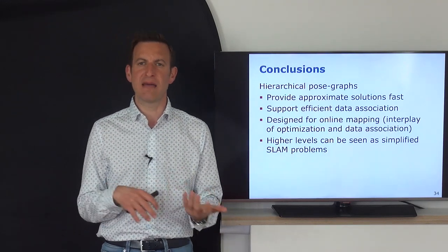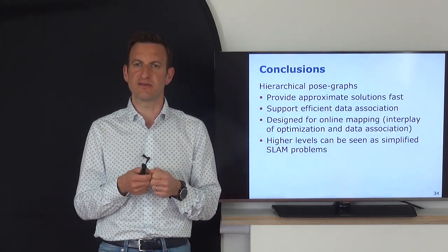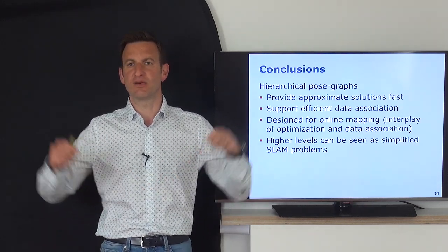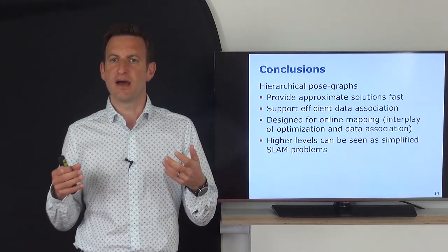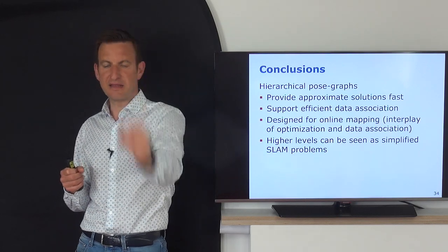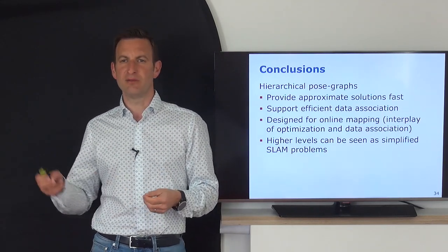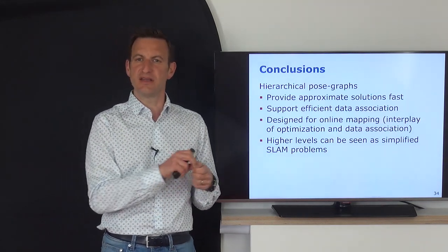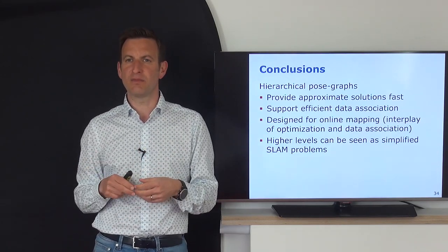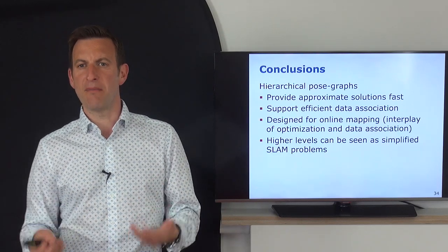They also have other advantages. For example, if you combine SLAM and planning, you could use this pose graph generated on a higher level, which still contains the connectivity information, the topology of the scene, to plan paths on a coarse level, how to move from a place A to a place B in a very efficient manner, because you have this hierarchical pose graph. That can speed up your planning if you want to drive an autonomous robot from one place to another, by automatically going up the hierarchy, planning on the higher level, and then going down. It's very similar to planning when you go with your car: the highway is the higher level and the small roads are the lower levels. You plan a path to the next highway entry, you drive on the highway, and you exit at a certain point. Planning on the highway is much simpler, and planning in the city is more complicated. It's a very good analogy, and you can do something like this with these hierarchical pose graphs to effectively combine SLAM with planning.